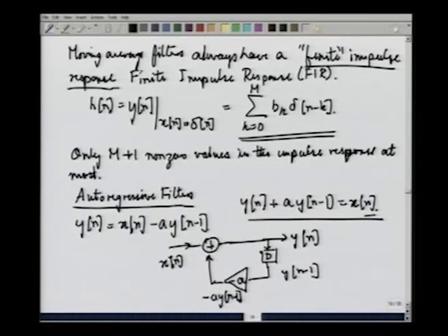And even though input is no longer being given, this would now act as the input. Delta n, or rather minus a1 times delta n, would appear as the next output, and this would go on and on, so that you would get an infinite impulse response, an impulse response with a support that is infinite.